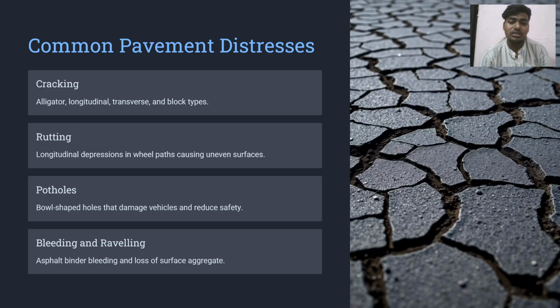It is caused by repeated heavy traffic causing the asphalt to deform, often due to a weak base or what we call subgrade, poor compaction, or asphalt mix instability. It is impacted by water. Water can pool in ruts, increasing hydroplaning risk and leading to uncomfortable and unsafe driving conditions.